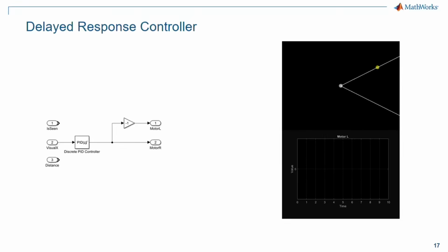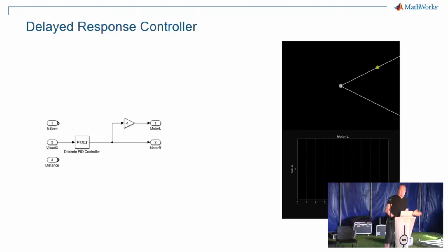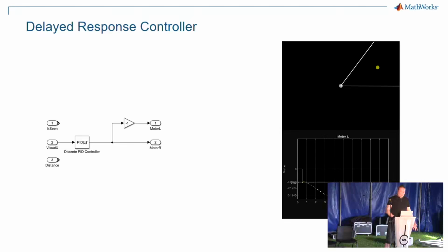So this is what a PID controller does, and you can take one of these blocks and you can tune the 3 parameters of how big of an effect each of these 3 forces have on the problem, and you get to something which, at least in theory, gives you the perfect kind of centering of the robot. You can see here that its initial guess as to how much force it needed to apply wasn't quite enough, so it kept increasing until it saw a response, and then it appropriately decreased the power until it centered on the tennis ball.